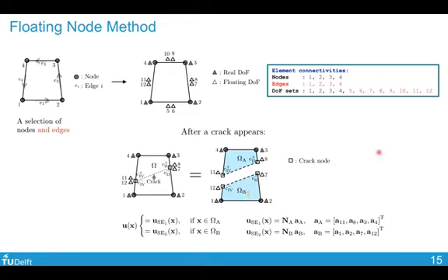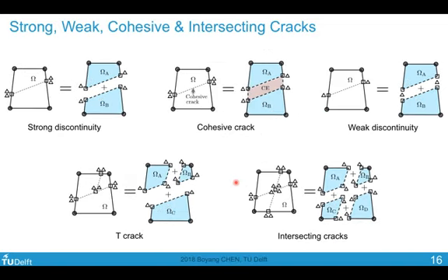With this method, we have a very flexible way of defining elements. So this is just a case for modeling a single crack across the domain. We could, of course, form a cohesive element in between. Now we have the crack nodes defined, we have the degree of freedoms available, we have everything that we need to define the cohesive element in between.